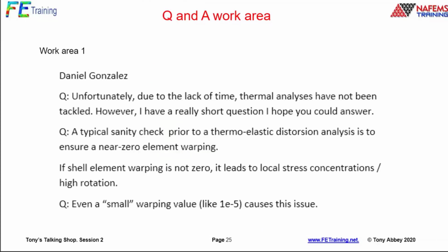Daniel says, unfortunately, due to lack of time, thermal analysis has not been tackled. I have a really short question. Hope you can answer that. Typical sanity check prior to thermal elastic distortion analysis is to ensure a near zero element warping. If shell element warping is not zero, it leads to local stress concentrations, high rotations.